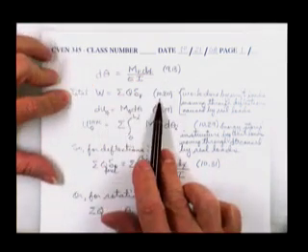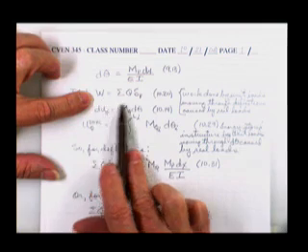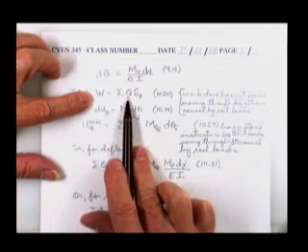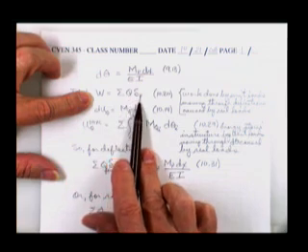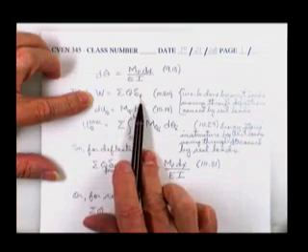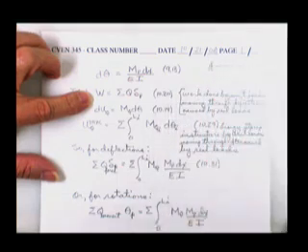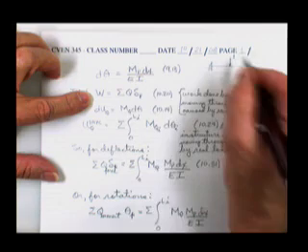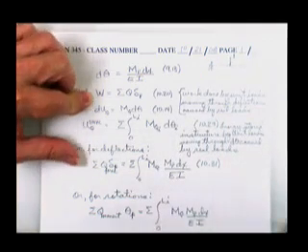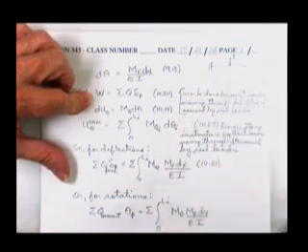Equation 10.20 in your text, we worked out how much work is done by one or more loads, dummy loads, unit loads, virtual loads, traveling through displacements on a structure that got displaced due to some real loads. For example, if you came out here on a structure and you put a unit load on there, it doesn't have to be unit, it can be any number and it'll cancel out. Then it'll bend the beam down slightly. You see that?